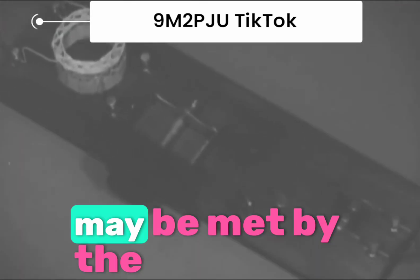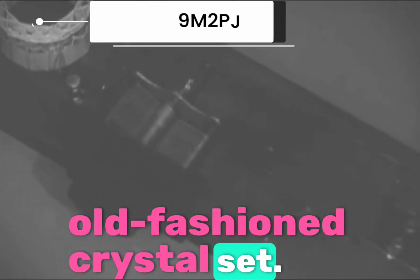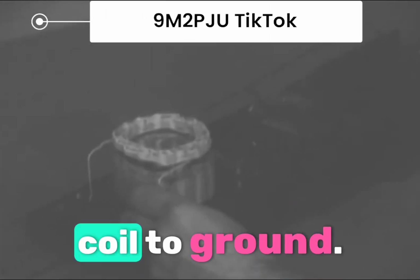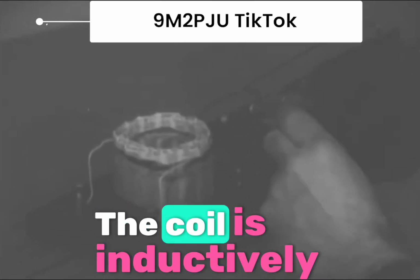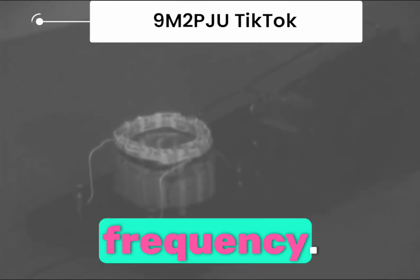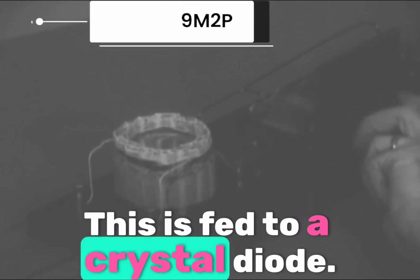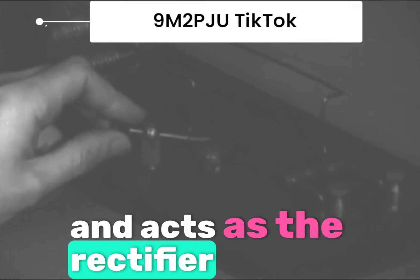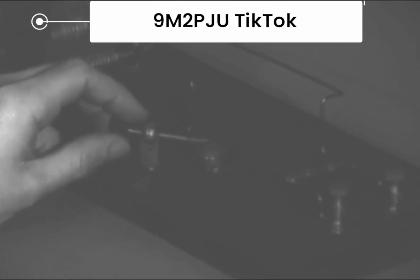These requirements may be met by the old-fashioned crystal set. The antenna is led through a coil to ground. The coil is inductively coupled to a tank circuit, which is tuned to the carrier frequency. This is fed to a crystal diode. A crystal diode is a semiconductor diode which passes current in only one direction and acts as a rectifier or detector.